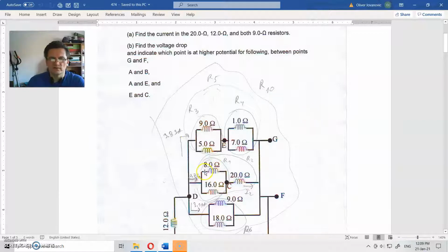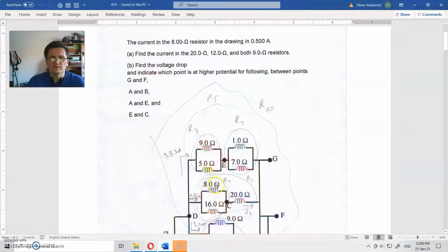But we have current through this part here, and we have its resistance. So we definitely know by Ohm's law that the voltage between those 2 points is when you multiply those two things. But voltage between those 2 points is exactly the same as the voltage between those 2 points. And then, when we find that current, this current through here and through here will add here and will make this E2. Let's say like that. For more precise, look for Kirchhoff's current law.